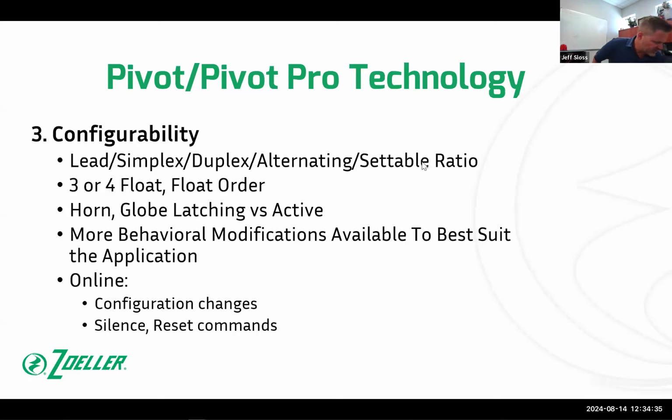People might say, oh, duplex and alternating, that's the same thing. And it kind of is, but what we're distinguishing between is a duplex panel. If the third float comes up, you expect that the second pump to also run. So they're now running simultaneously, which is fine. That's the way duplex panels work. But we added alternating just as a way of saying, you know what? There are situations out there where you never want two pumps to run at the same time. And we've been given many examples of this.